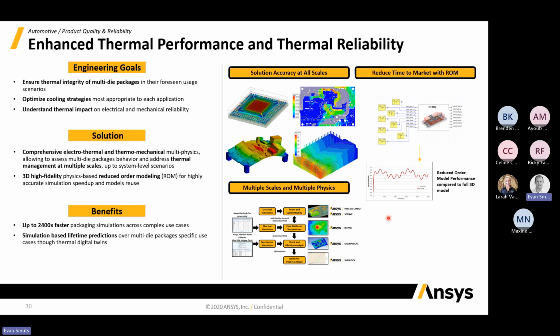And I think it's very important to also just remember that these kinds of electromagnetic thermal simulations are actually a bit of an iterative or coupled approach, in the sense that as materials heat up, their material properties can change, which then affects their electronic performance, which then again changes their temperature. So we do need to consider that